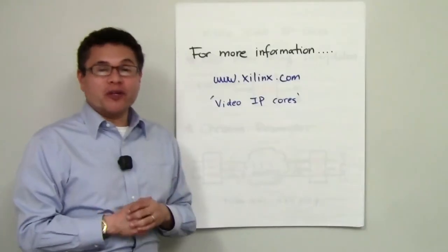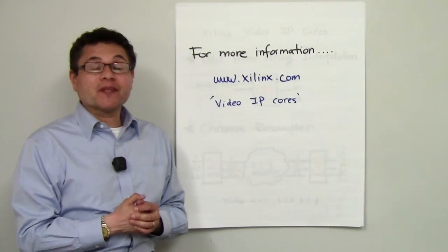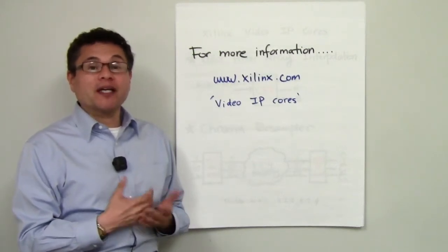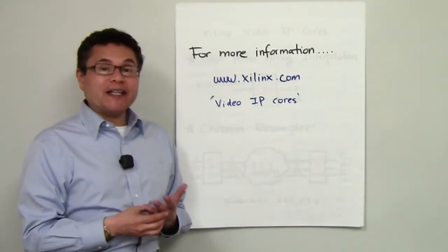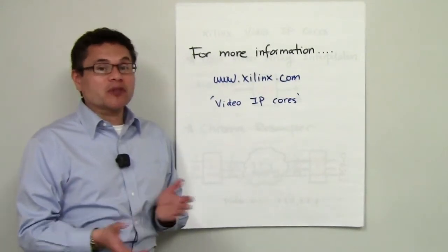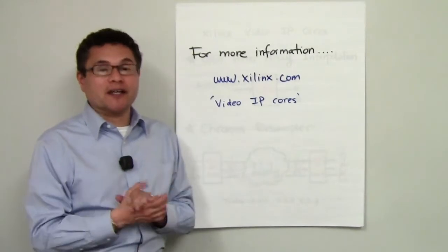Today we have very briefly touched upon various image color formats, subsampling, and ways of storing image information in memory and transmitting. We've looked at various ways of representing the image data according to the human visual system, both in the RGB and the perceptual domains, for instance, YCrCb.